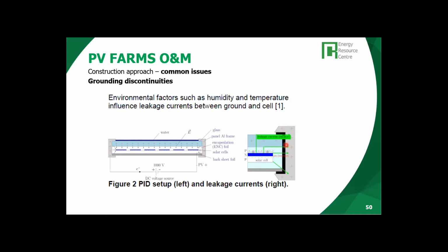Yes, I am sure there's a leakage about the structure, the aluminum. There's a leakage of some electrons, of some current. Some electricity was kind of leaking, right, in a way. Yes, from the panels, through the structure and to earthing.